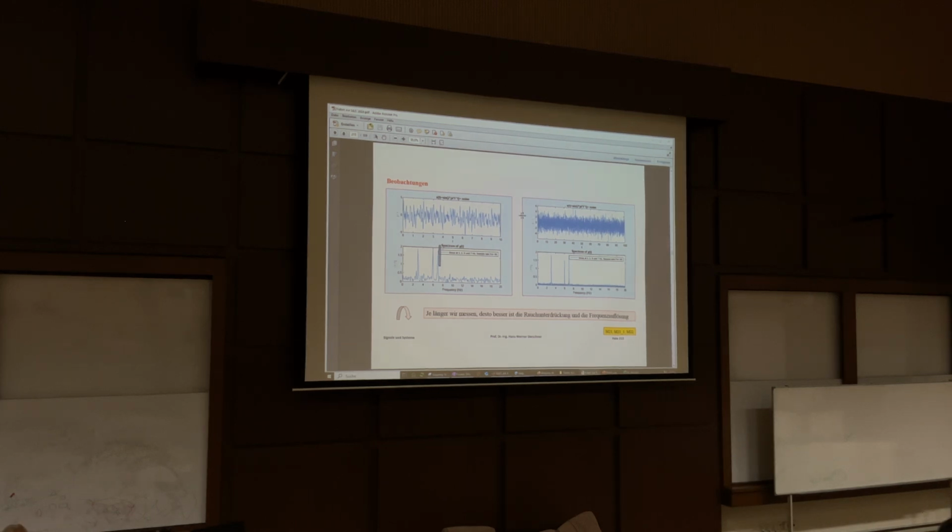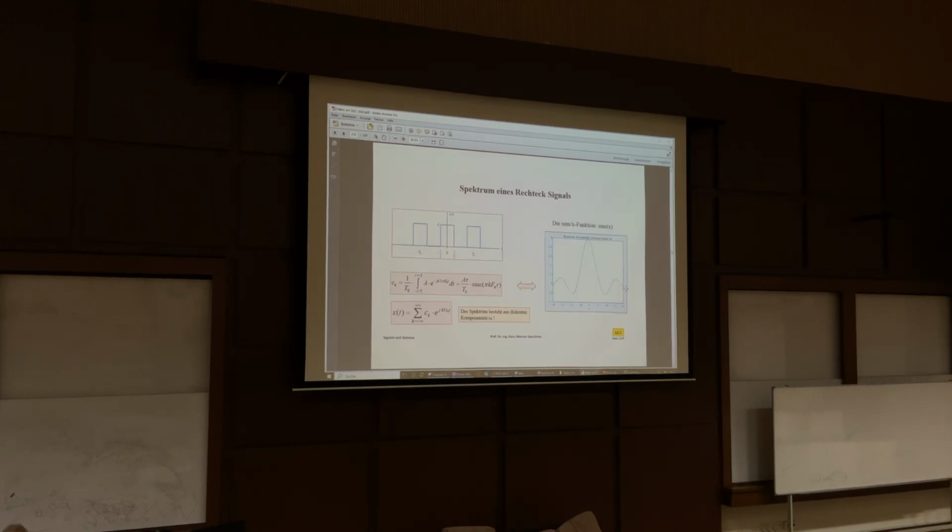If we enhance our measurement time, so the longer I measure, the better the results are. And you see here a longer measurement. Here we have 10 seconds, here we have 100 seconds. And then the same spectrum, but it is clearer. You see it's finer, more distinct, these peaks. And you see also the noise is further reduced, because it makes, I could say more or less, an average over it by doing the spectrum analysis. Okay, that's this one with a sinusoidal.